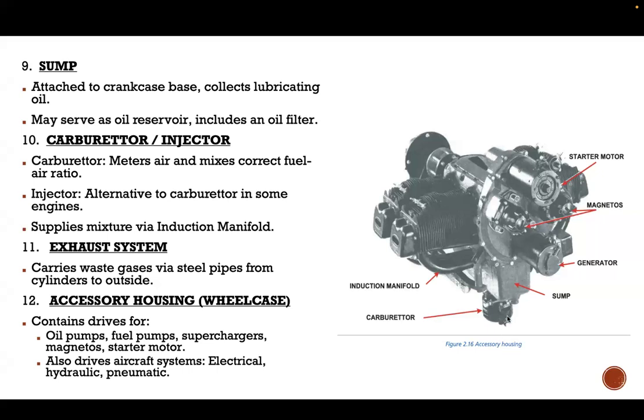Depending upon whether we are climbing up or descending down, we are going to adjust the amount of fuel that is going to be supplied into your carburetor, which basically works on Bernoulli's principle. That is, we are going to create a low pressure zone by using a venturi, which sucks in fuel from the throttle nozzle, and it is going to go into your engine. And we already know that our carburetors are prone to icing also.